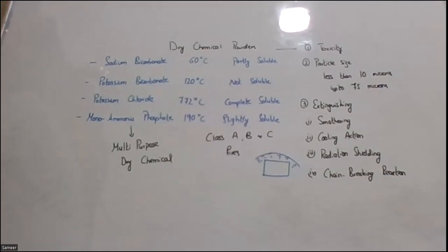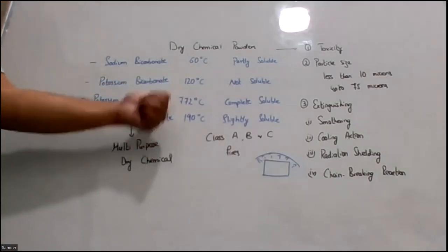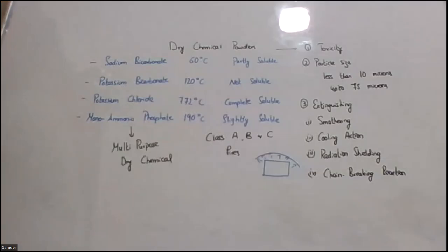So when you want to apply, let's say 1200 degrees Celsius, but 1400, 1800 degrees Celsius, and it goes higher and higher. You can see none of the dry chemical powders is going to sustain that much. When you apply it, before even reaching that temperature, it's going to get decomposed. So that is why we don't use dry chemical powders for metal fires.